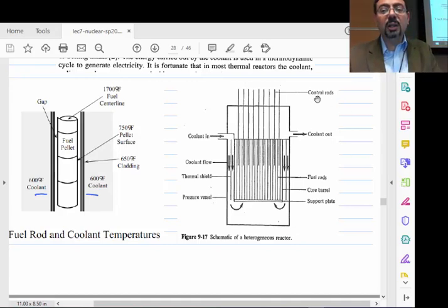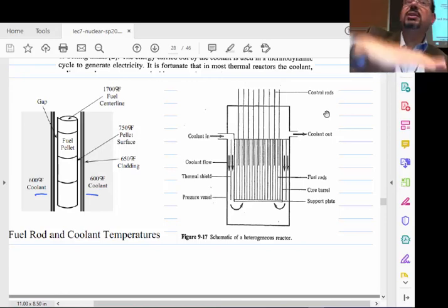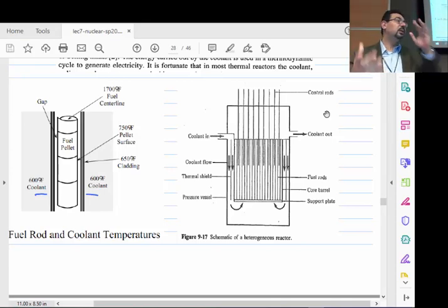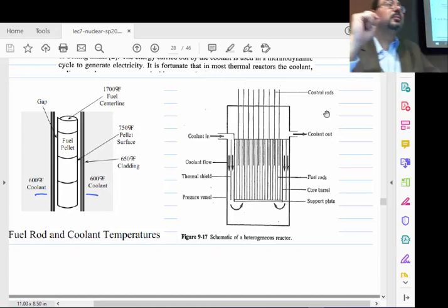And look at this, those are the control rods. What are the control rods? We put them in and they kill the reaction. So the reaction is supposed to be dead, but there is also the decay heat. Even if you insert all of them correctly, they didn't do this in Chernobyl because they didn't have time. But in Japan they claim they did, and they did actually. So the control rods came in and shut down the reaction, but still the fuel rods are hot and they need to be cooled all the time. And without any pump running, and with the diesel engine that was supposed to run flooded by the tsunami wave, that's why it couldn't run.